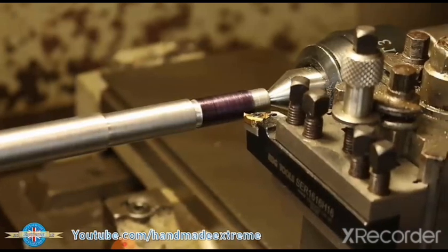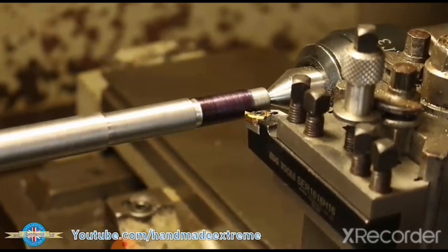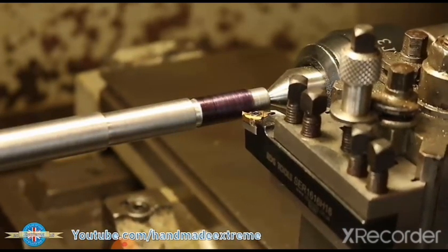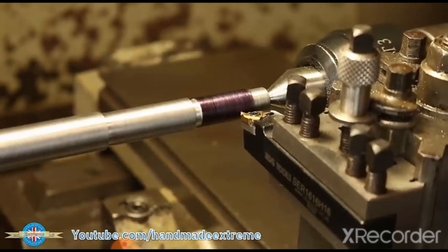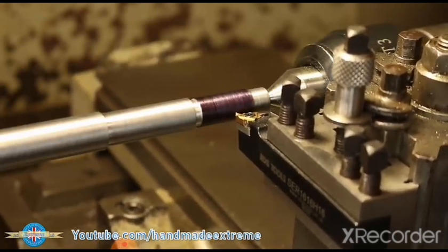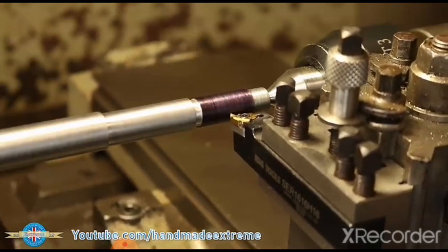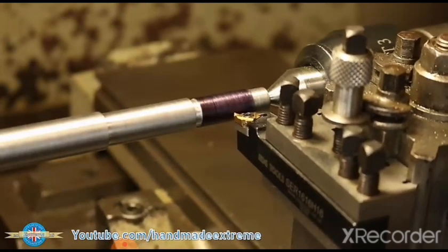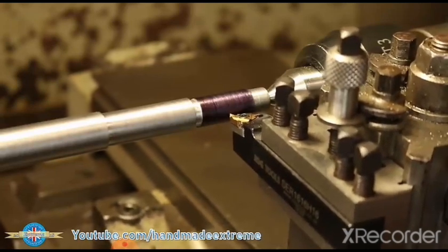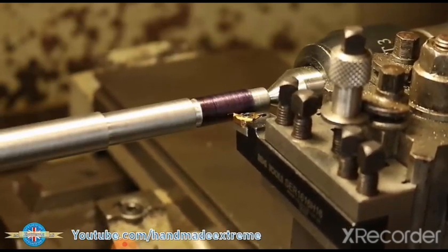The next step is to just bring the tip of the tool into contact with the part. This is going to set your datum. Now, I like to move the tool back and forwards along the Z-axis as I'm doing this, so that the tip of the tool scratches a line into the inked surface. That way I don't go gouging it in too far, and I just touch lightly. There we go.